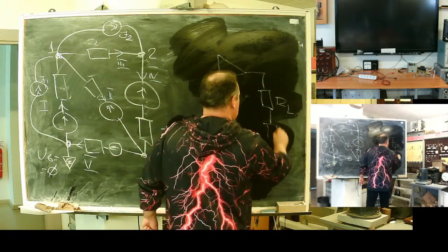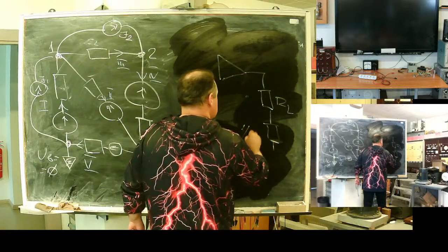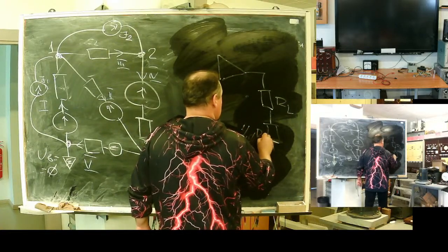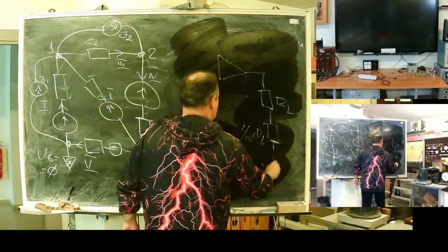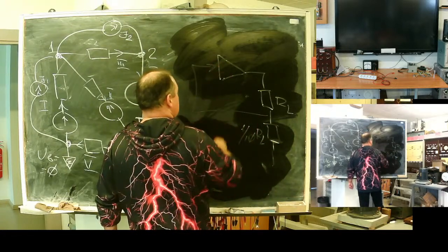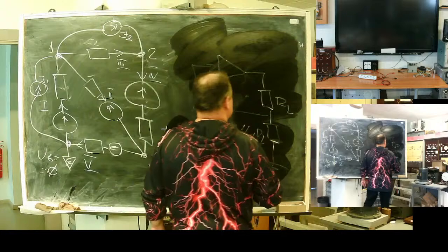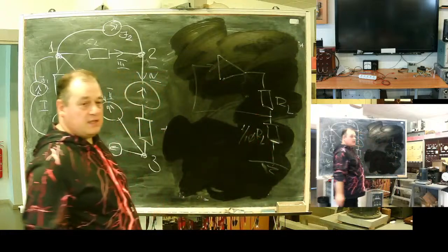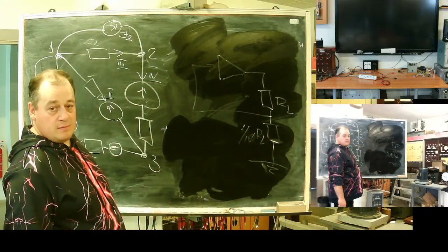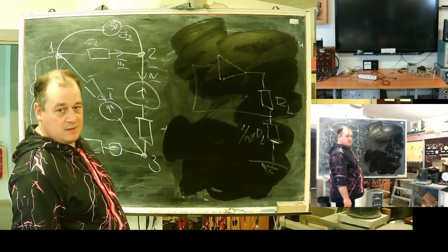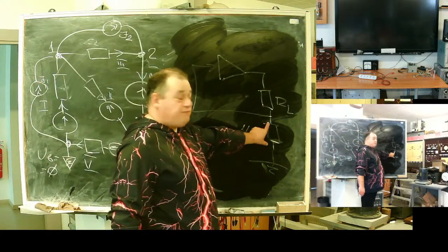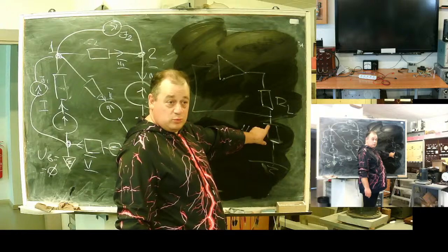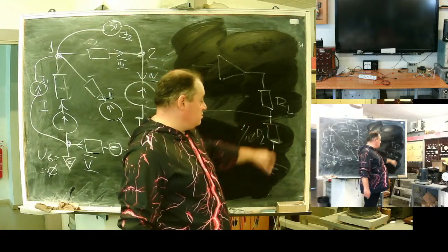Load. Add a small resistance, something like 1/10 of the load. And take feedback from this resistance. What will you get? A current source, because feedback is by the current, not voltage. This is a shunt resistance.